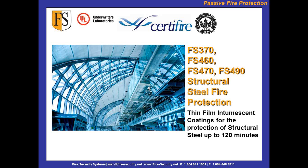What you find is that very large steel sections have a very low HP/A value because it takes longer for them to lose their integrity. The smaller the section, the larger the HP/A, so it has an extremely thick coating put onto it, because that small section is going to lose its integrity.